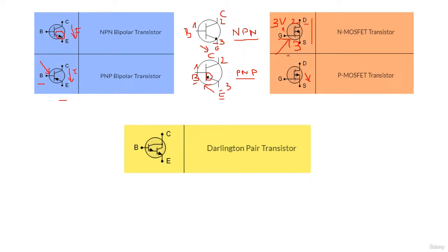That's why we use the MOSFET in switching mode, because the MOSFET can be on and off, on and off, in accordance with the voltage or the enable signal that arrives at the gate over here. So this is the symbol of the transistor, and this is the symbol of the MOSFET.